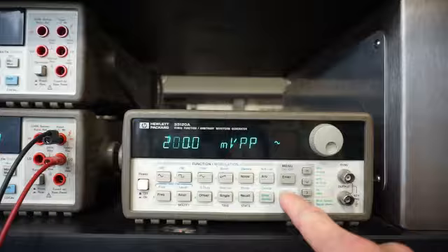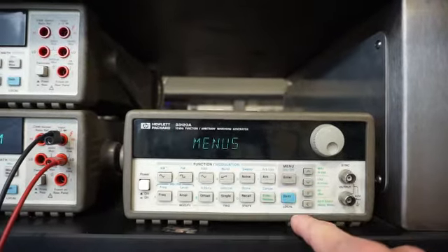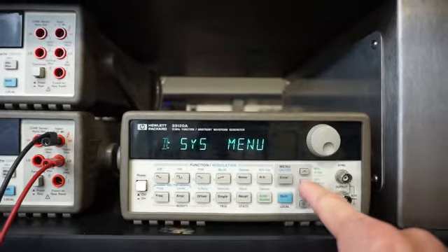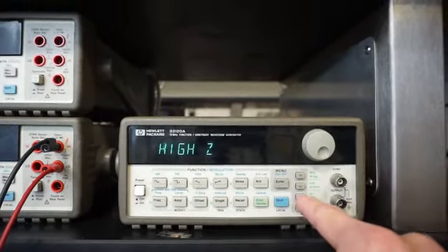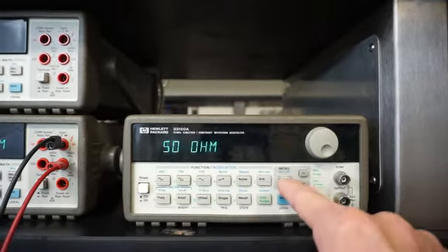To shift between modes on the function generator, hit Shift-Enter followed by 3 right arrows, 2 down arrows, and then one more right arrow to actually change the mode. Press Enter when finished.